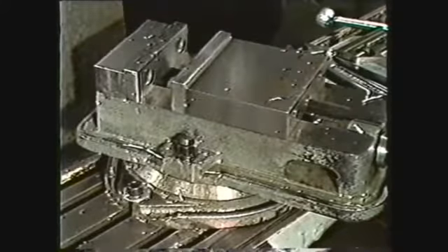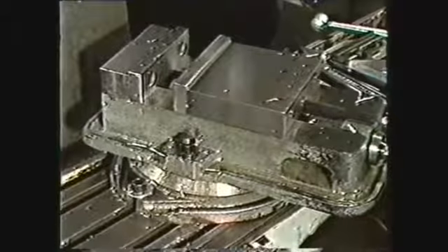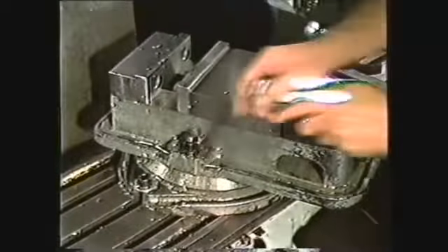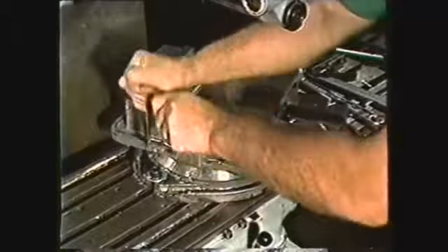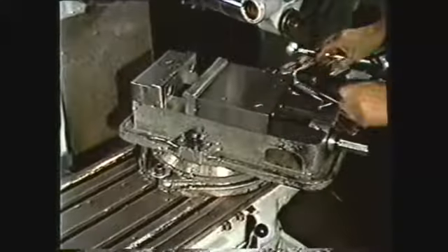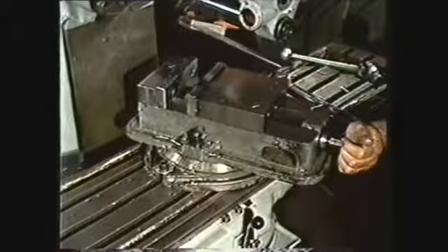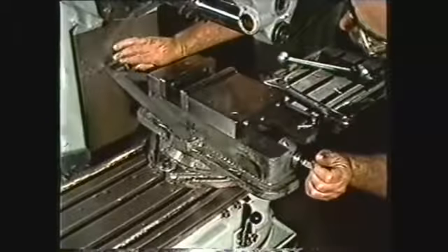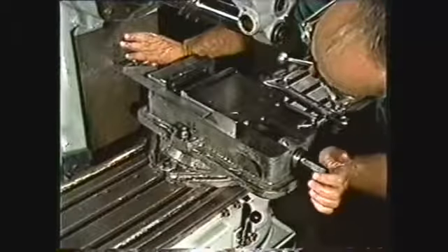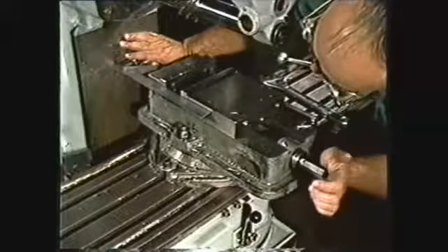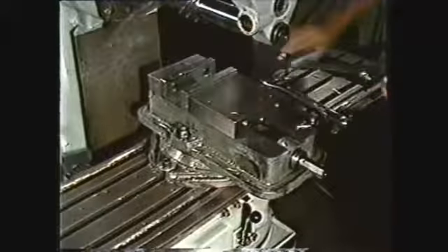When performing plane milling, the work is usually held in a heavy machine vise, which should be rigidly clamped to the machine table. Since plane milling is usually a top surface operation, the alignment of the vise on the table is not as critical as would be needed to mill steps into the side of a workpiece. Therefore, alignment of the vise can generally be satisfactorily made with a square.